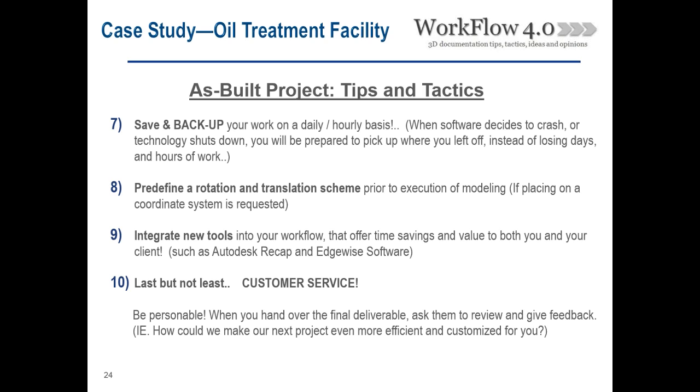If you are doing a scanning and modeling project, one of the questions you want to ask is if it needs to be on a coordinate system. And if the answer is yes, then make sure you know how you're going to do that before you get in the project, and which software it's going to be inside of. Are you going to do the point cloud and the model, then move the point cloud or model afterward? Just know how you're going to do that.